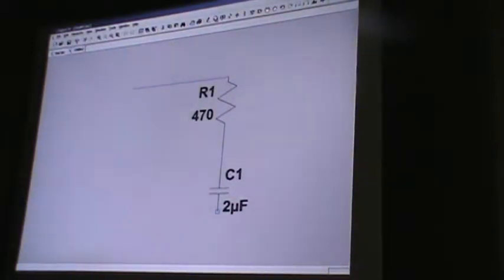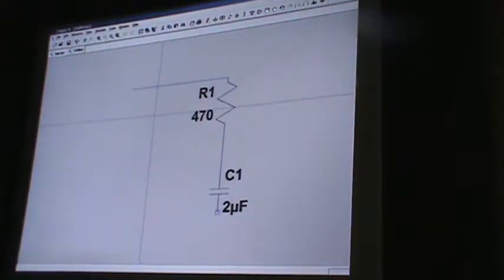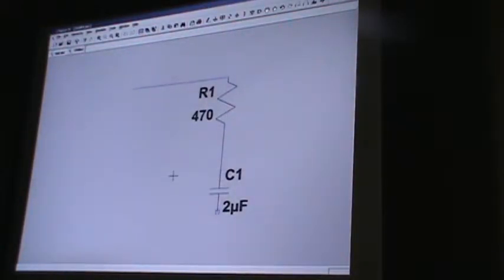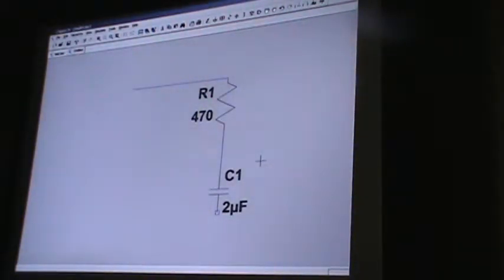You need to click on the wire, and when you've got the cursor that goes all the way across the screen, that's where you've got it. You just right click, left click, left click, regular click, and then drag. But sometimes you want to leave a little leader of wire down so that you're away from the initial point where you contact the component, so that when you move the component, if you have to rearrange things, you don't have the entire trace following you everywhere. Right. You kind of want to leave a little bit of a grid separation.